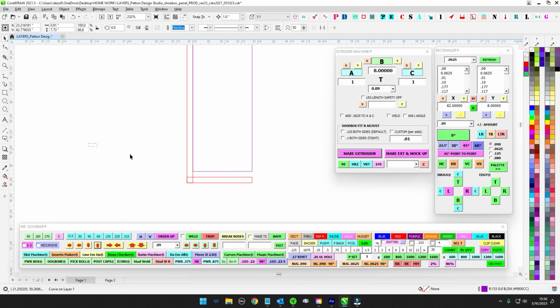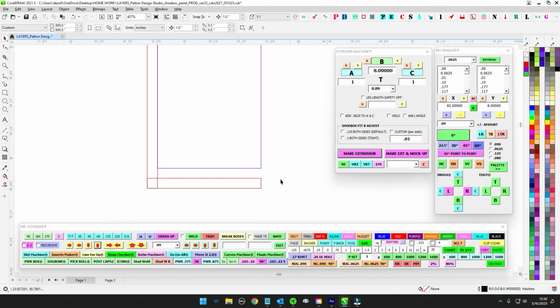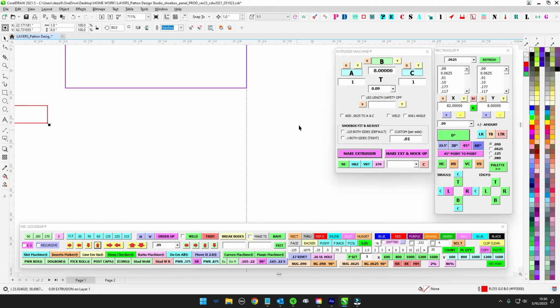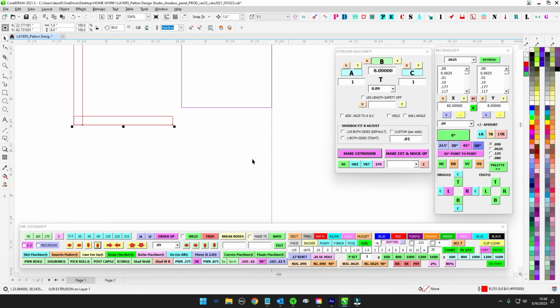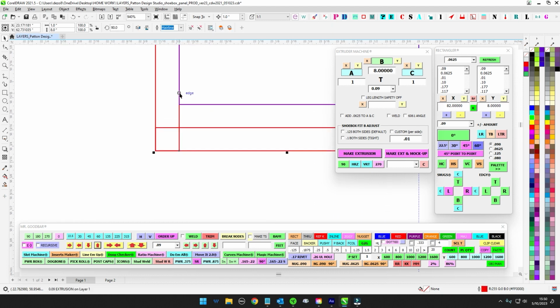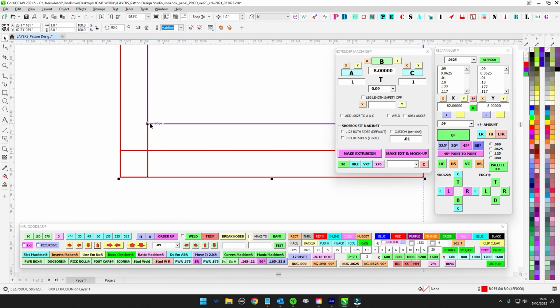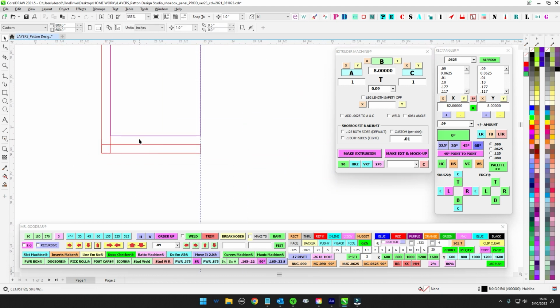So there's our clearance. And now you also have to clearance the front, because let's say this is your wall or whatever, right? We want the face to bonk fully against the wall, bonk. But we don't want this to conflict, right? So when we bring this up, this is zero clearance right here. And in real life, this is going to be sticking out a little more, a little less, whatever. So we also need to clearance it this way.